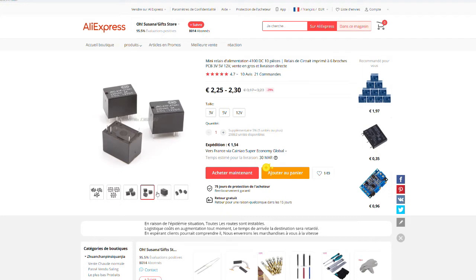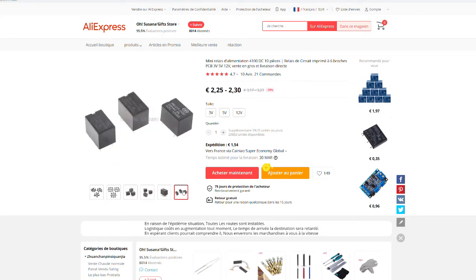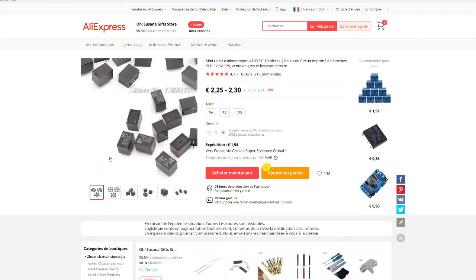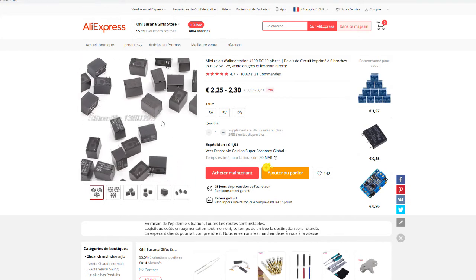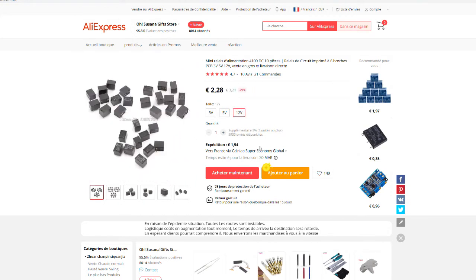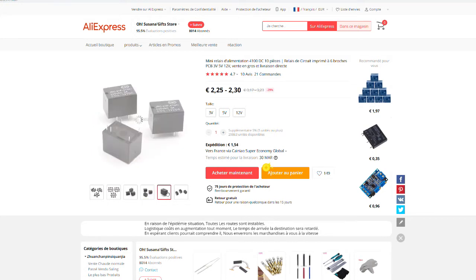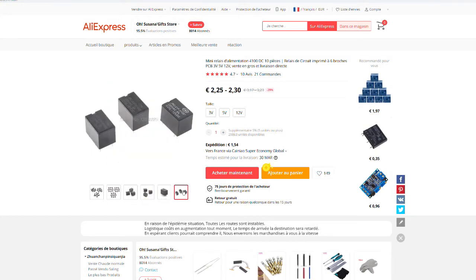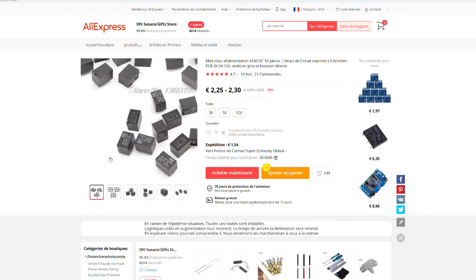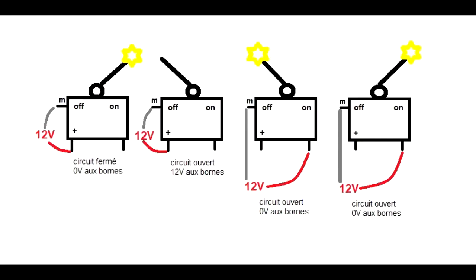One thing you must know about LeoBodnar boards is that you can only plug a button on the pins, and the switches and buttons with integrated LEDs are supplied by 12 volts, and if that voltage goes to the board, you may fry it. That's why I use a relay to isolate the 12 volt circuit from the LeoBodnar board. So this is a wiring diagram of the only two ways of wiring this switch.